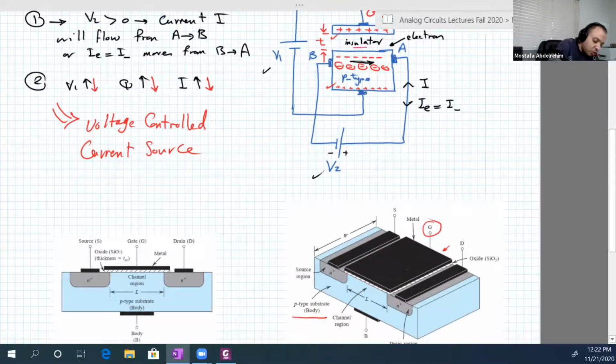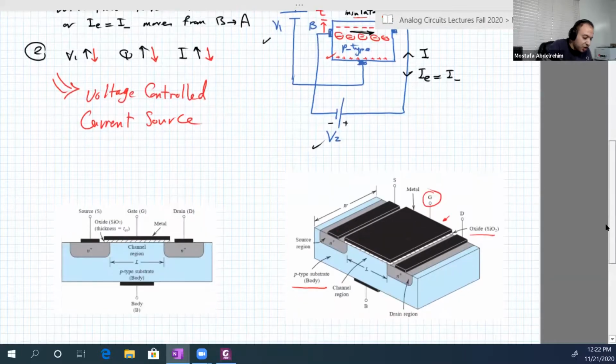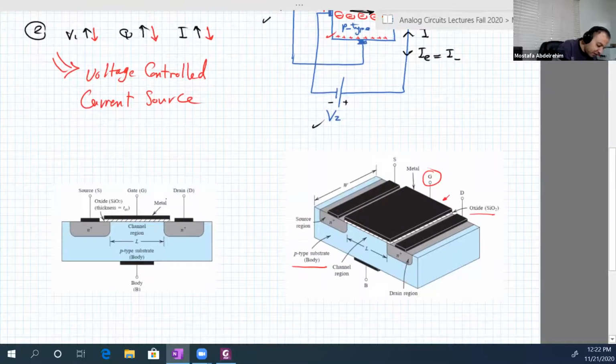And the insulator in between is the oxide or silicon oxide. This dashed area here, white dashed area. And the two terminals, A and B, are just another N-type regions, and we will explain in a moment why they put them as N-type regions inside the P substrate. If we look at the cross-section area like this, so again, here is the metal, here is the P-type region, and here is A and B.